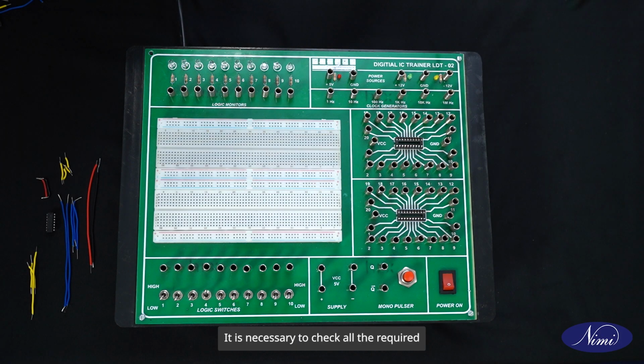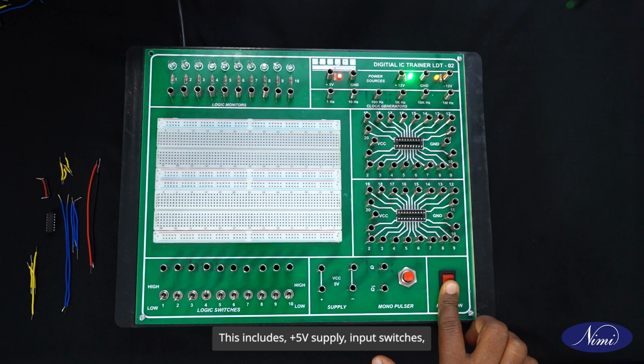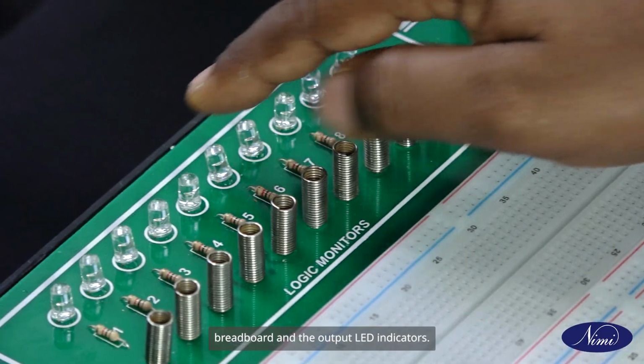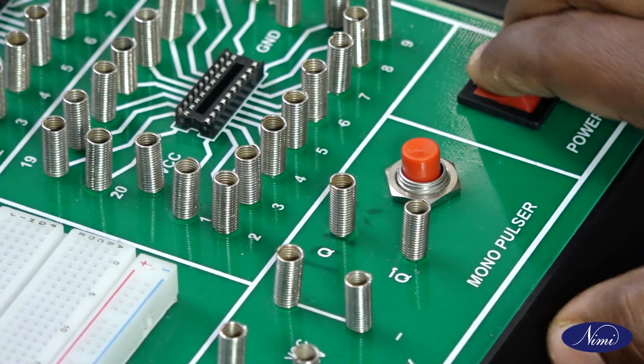It is necessary to check all the required sections of the digital IC trainer to ensure its working condition. This includes the plus 5 volt power supply, input switches, breadboard, and the output LED indicators. Make sure to thoroughly inspect each part and verify you have the full set before beginning assembly.